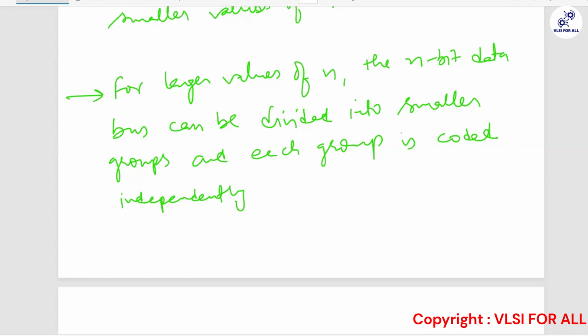So we can shut off that power. We can shut off the toggling of that clock. It means there will not be any unnecessary transitions on the clock, and that will not affect the functionality of the circuit either. That basic idea is known as clock gating.